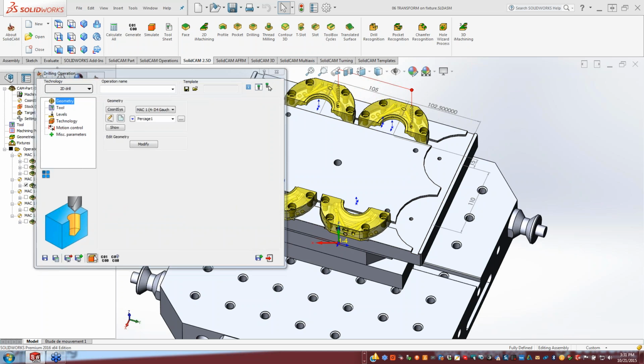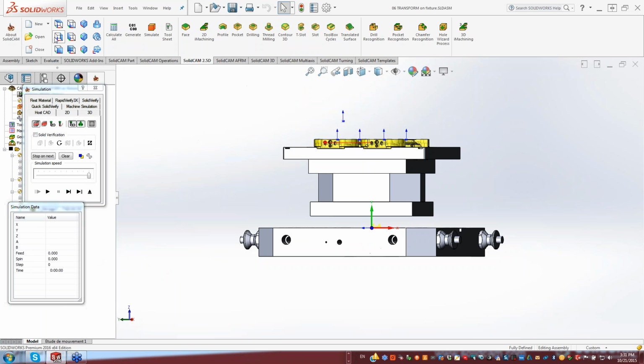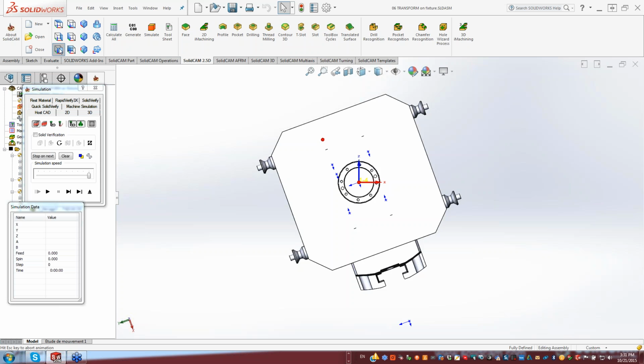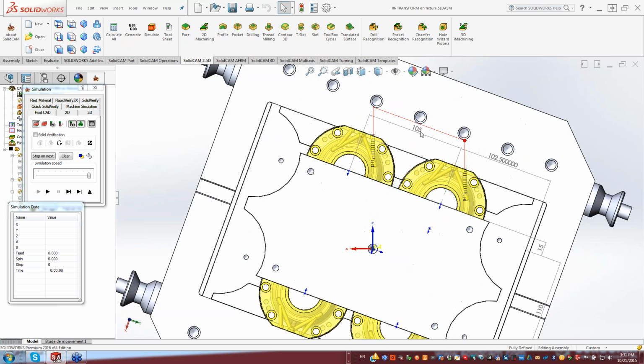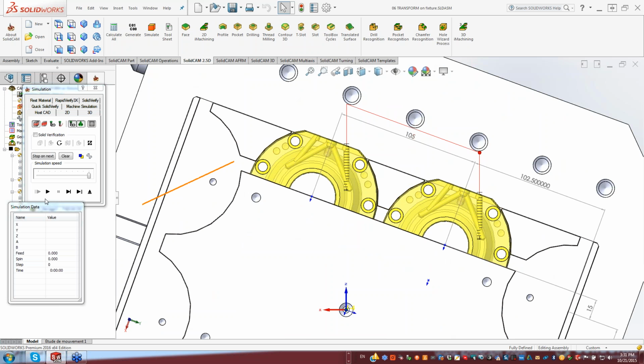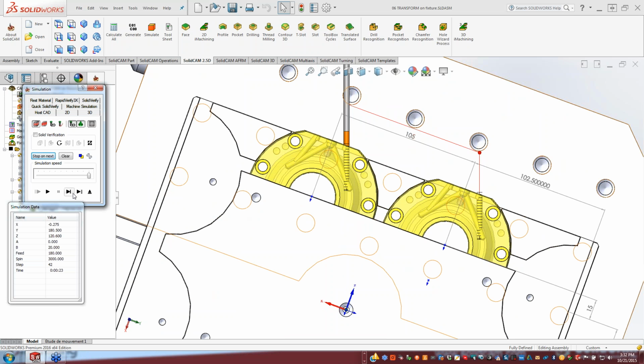And if I were to run my simulation now, let's take a look, not from the top view, but rather from this side view over here. Okay? You can see our first step is in that particular hole over here. And now it's going to come across, go directly down exactly where it needs to go to on that hole over there. Okay? Drilling them both out using the option of transform, but according to a specific home position vector.